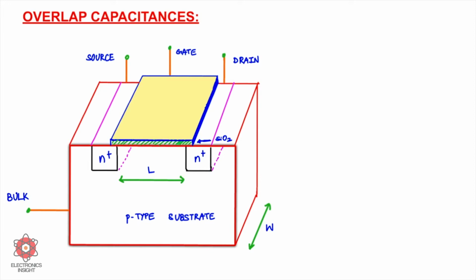So we have discussed CGB, CGC, CGS and CGD in 3 different regions of operation of the MOS transistor. And the second thing that we are going to concentrate on is the 2 special components of CGS and CGD, which are caused by the lateral diffusion under the gate and the thin oxide. So here you can see that there is an overlap between the gate and the source. In this portion the source and the gate are overlapping. This you call CGS overlap,